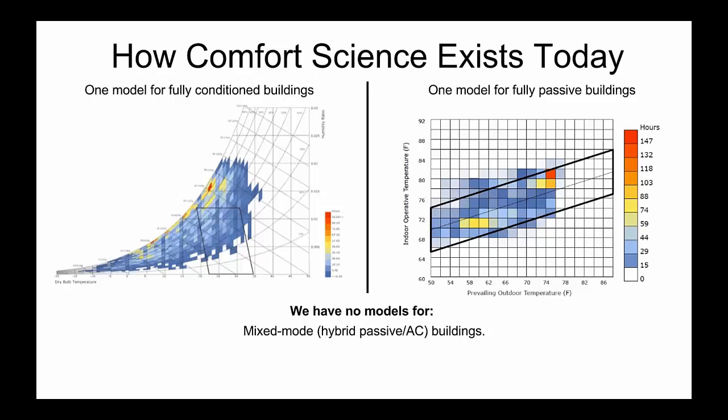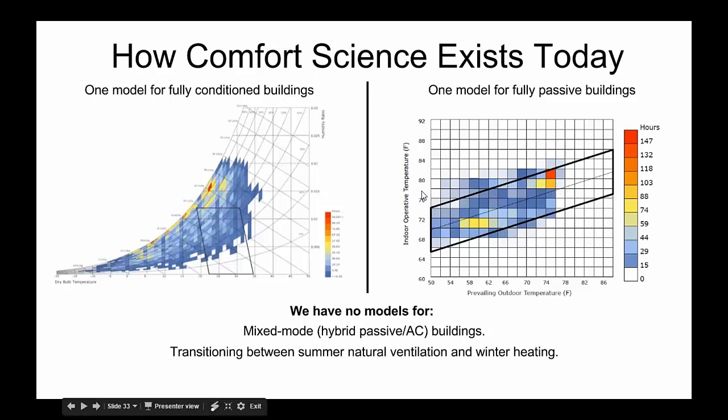There's really no recommendation for that, and really ASHRAE and the ISO pretty much just say, we don't know, use PMV is really the suggestion right now, but it's clearly not a very satisfactory scientific answer. What else don't we have a thermal comfort model for?